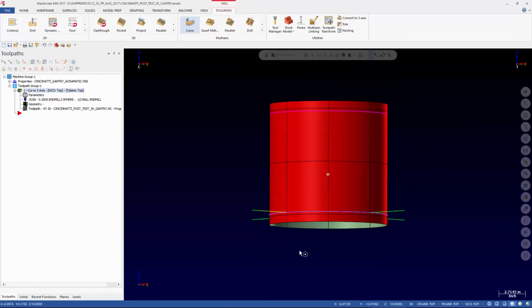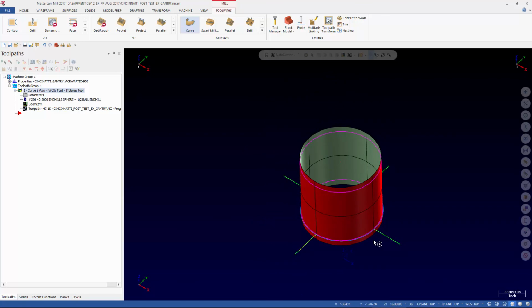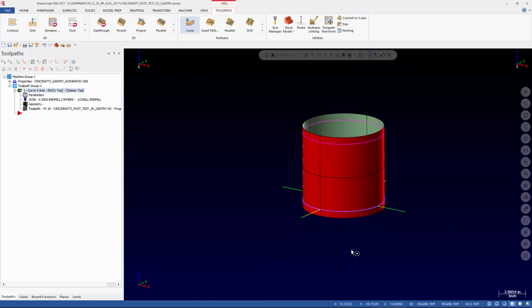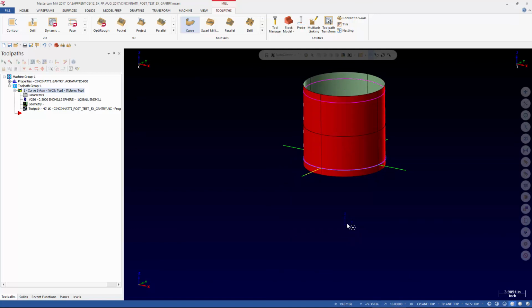So it doesn't matter if we're using a gantry or a trunnion machine, the first test I always do is spin a circle. It's so easy. Create a cylinder, figure out how big the piece is, usually around the size of your platen, or whatever will clear from the center of rotation.